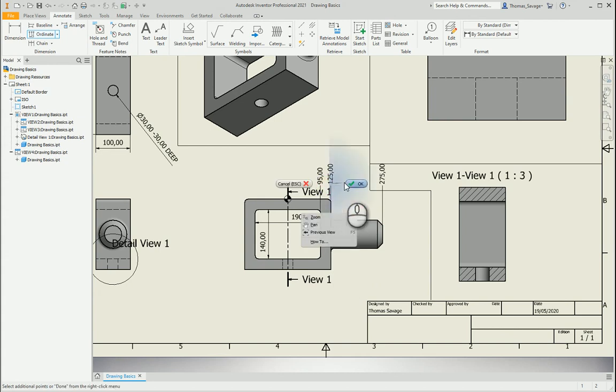Again, right click, okay. So now we have this datum here that we can place anywhere. This is 95mm away, this is 125, this is 225. It's not the baseline, but you have a datum to place, because if we wanted to measure from here, we don't have a line to select as the baseline, so this just creates a datum instead, so you can do it from anywhere. So that's, again, handy if you have a lot that you want to measure from a point, basically.